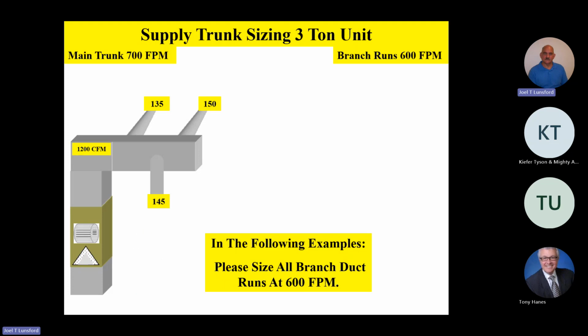So when you transition down, you want to make sure that you don't take any more than 40% of the air in that particular main trunk section. Don't take any more than 40% off. And like I said, typically we find that most contractors, it ends up being about 2. Normally after about 2 takeoffs, or maybe 3 smaller or medium-sized ones, they'll go ahead and transition down, which normally works just fine. So good questions.